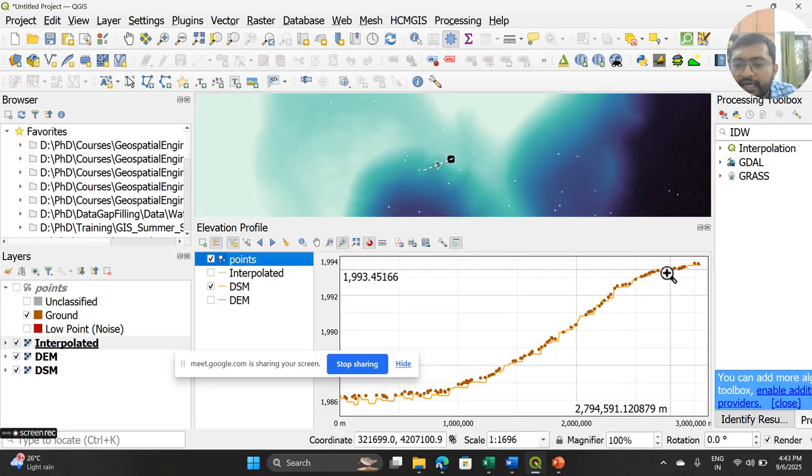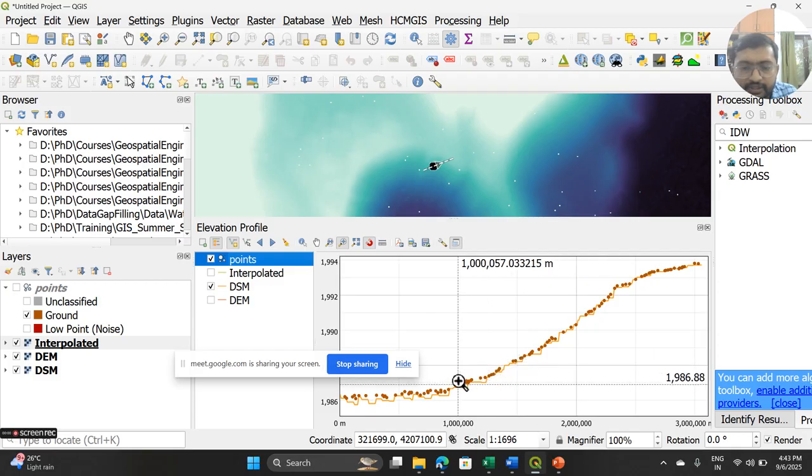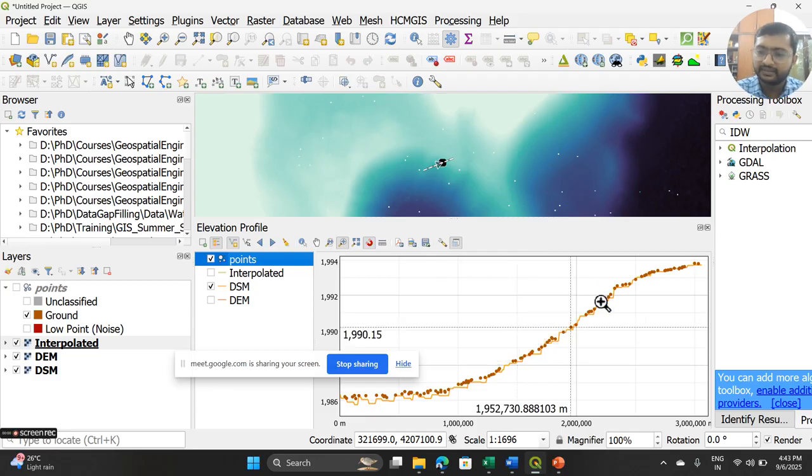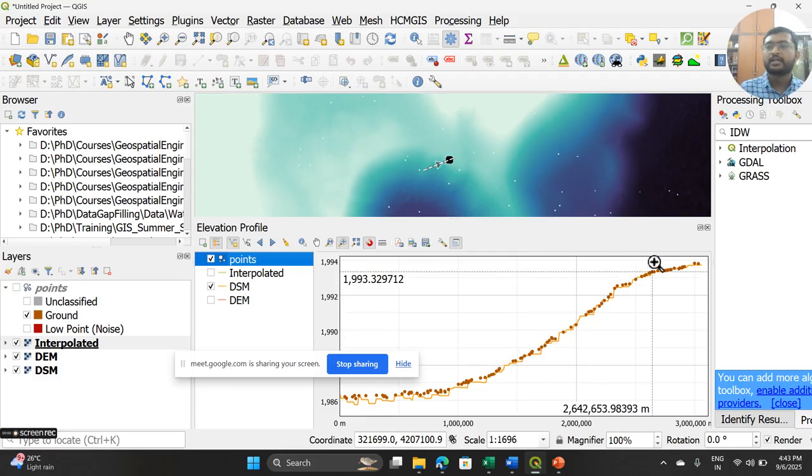So your point data will look like this, which you can see as points. And then there is a conversion of that into continuous data as pixels. Once you plot these pixels, it will give you the idea about the surface. You can find out the slope, you can do how water will flow, and you can do lots of analysis after this.